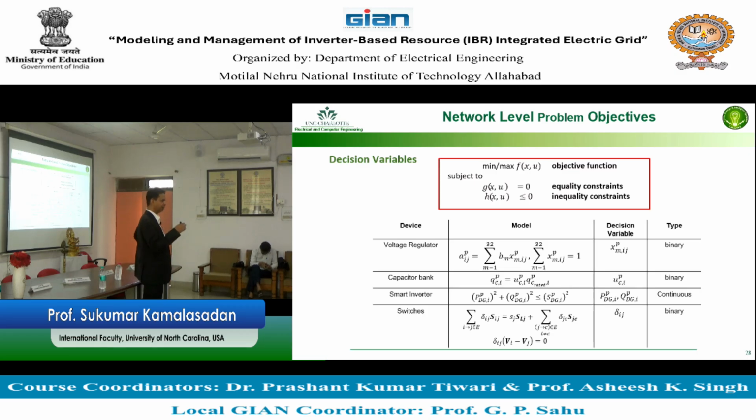It can be done in discrete form or in continuous form, but it's continuous operation output. The second type is called an on-off controller, where you get a decision which is binary in nature, 0 or 1. The third type of controller changes set points in percentage, 50%, 100%, 30%. Such controllers are generally called discrete set point controllers.